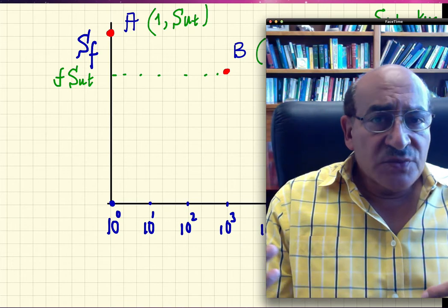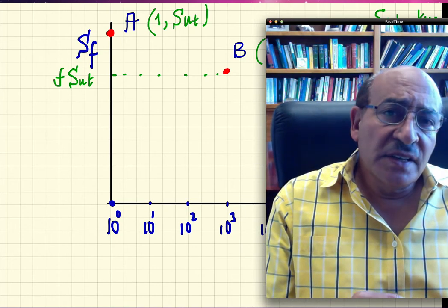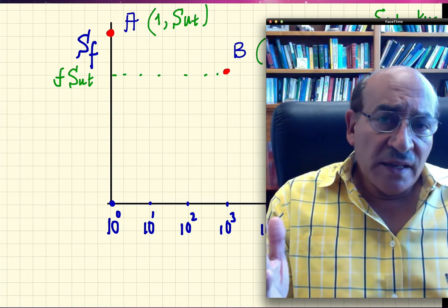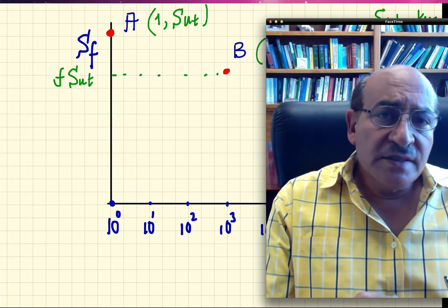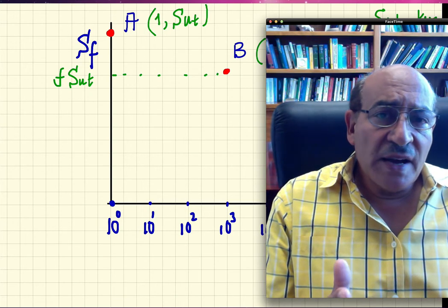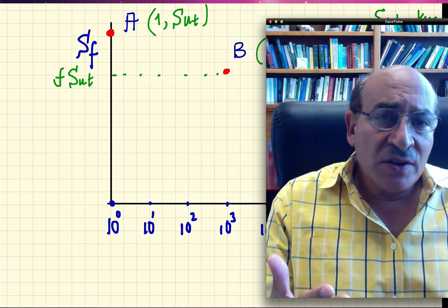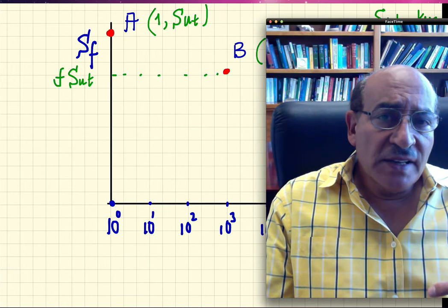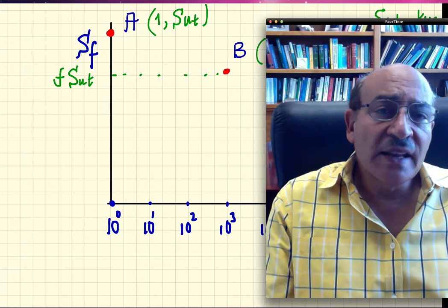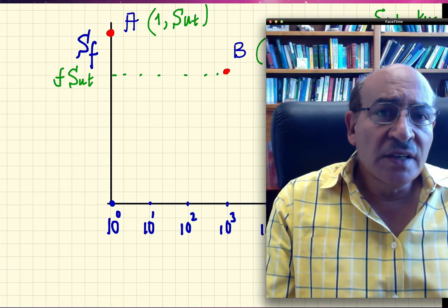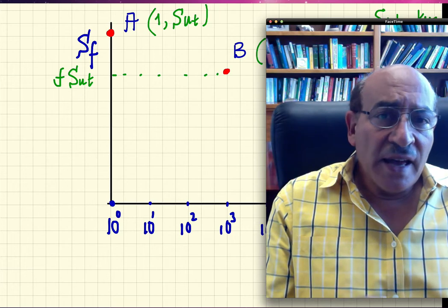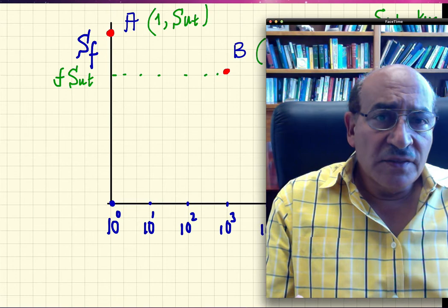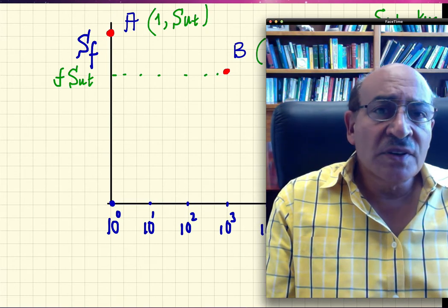As we mentioned in the previous lecture, any linear equation on a linear log plot is equivalent to writing the relationship as a power relationship. So we're going to assume a power relationship for low cycle fatigue and another one similar for high cycle fatigue, and then find the constants in each one of the power relationships from the coordinates of these 3 points.